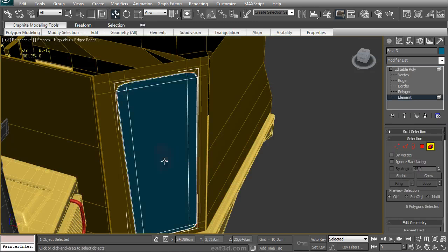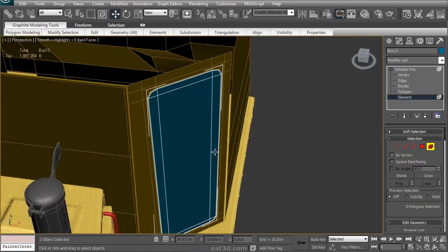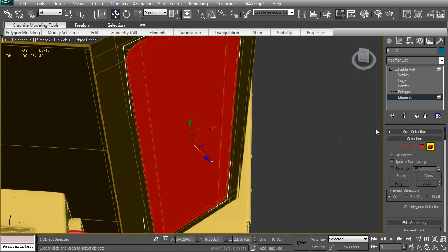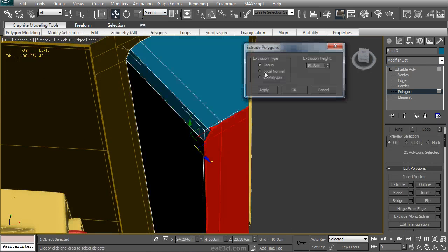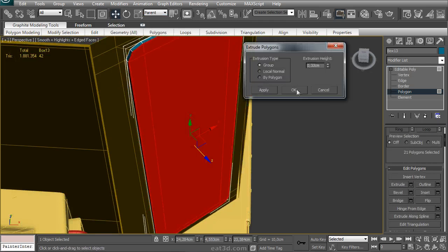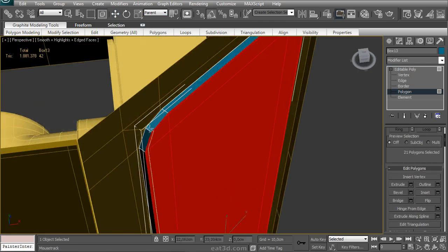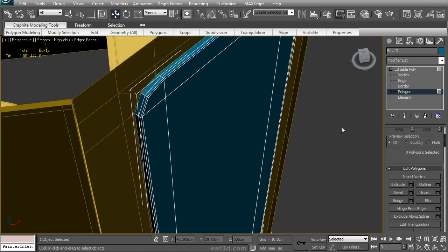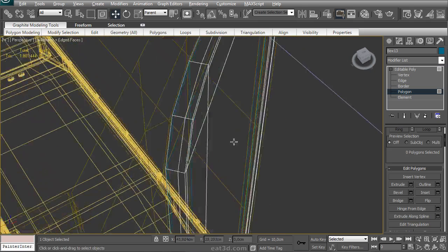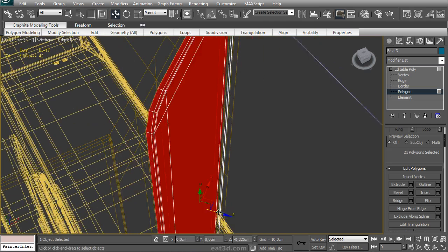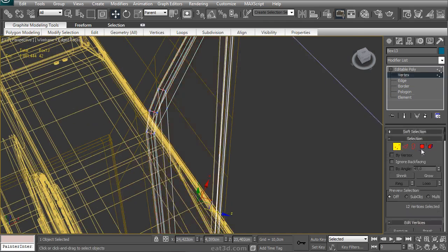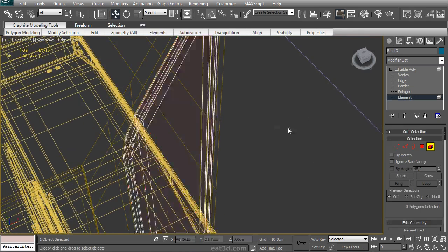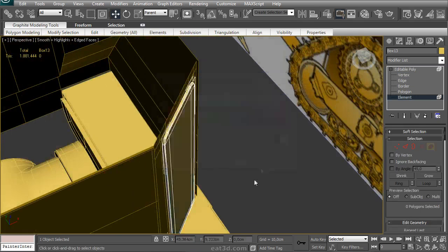And now I just attached the door to a cube that I created using the AutoGrid method. And that just simply resets the orientation of the door. Make sure that it's oriented in the way it's actually facing, instead of inheriting the pivot point of the object it was created from. So that just looks better. All right. Duplicating that back in. Just making sure the door has a front and a back side.